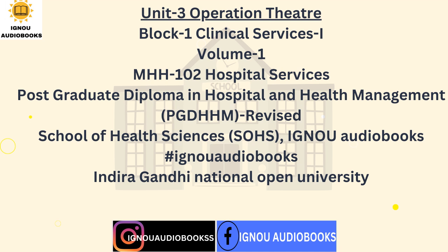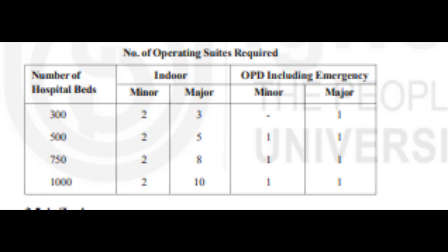3.5.2 Size of the operating room. Minimum clear area for a general operating room is 40 square meters. Cardiovascular, neurosurgery, orthopedic and other specialized procedures which require additional equipment need minimum clear area of about 60 square meters. An additional adjoining room to the main OT may be needed for heart-lung machines for cardiovascular OT.